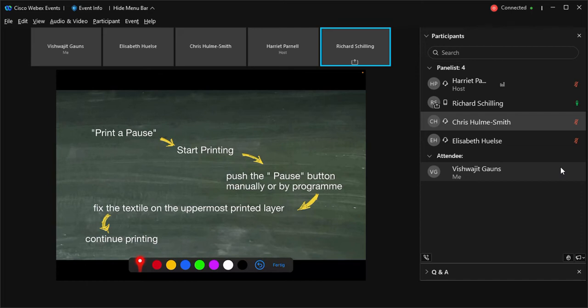And on the other hand, you want to have a plastics material which is solid in a normal human environment. So that means that the glass temperature and or the melt temperature of your polymer should be well above, say, 50 degrees centigrade.